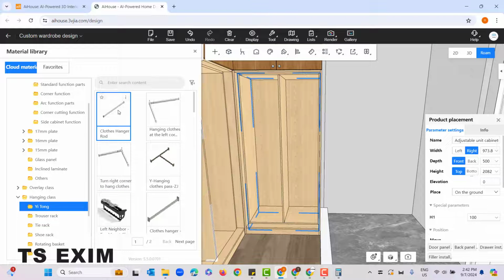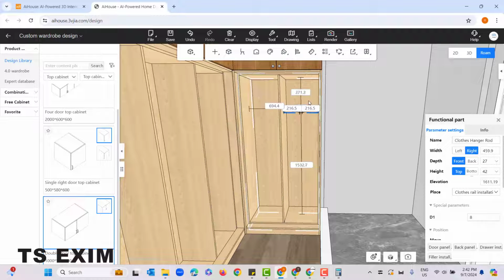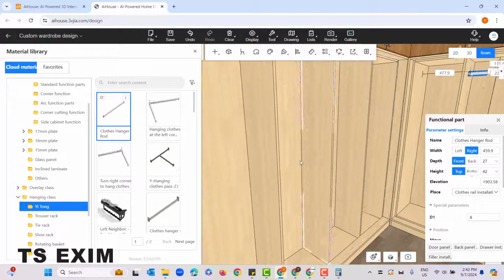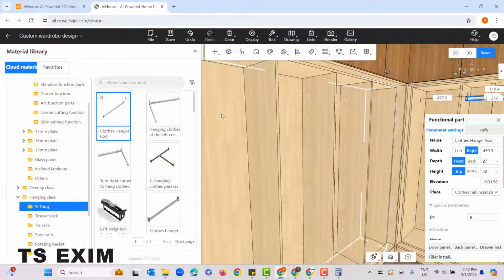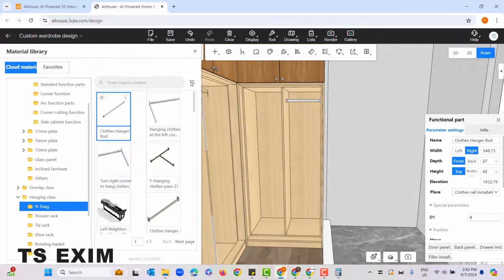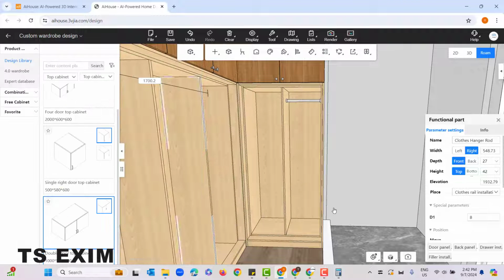This is the closed railing. Okay, you can drag any railing you like. Just drag one only. Later I will teach you how to copy. Okay, remember this one also need to drag inside. Cannot double click. And then you drag another one to the left. Alright, then you can close the library. So this is the railing.